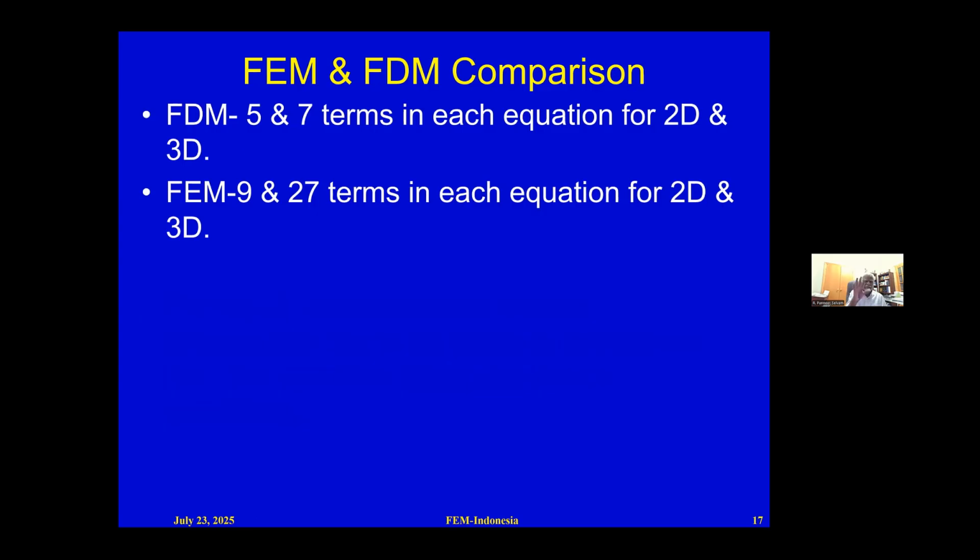When you use segregated, what do you mean by segregated? Solving U, V, and P each separately, and then doing Newton-type sub-iterations overall to satisfy everything. If it is explicit for convection or momentum, then you only solve the pressure and go to the next time step.